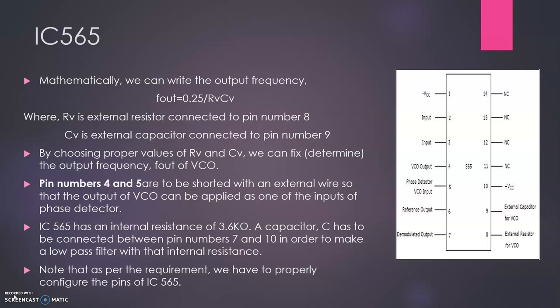The IC565 is basically used in applications such as PLL demodulation and signal frequency divider or multiplier. The device is specifically designed with a highly linear VCO for low distortion FM modulation. The device, being cheap, can be used in applications where cost is considered.